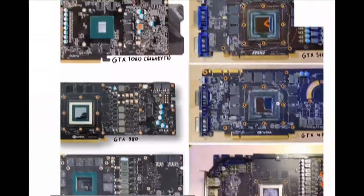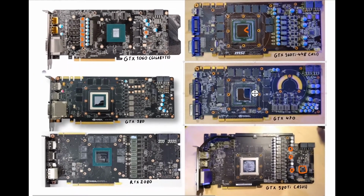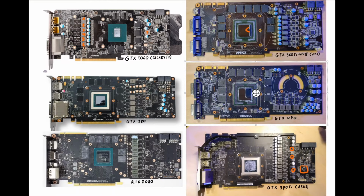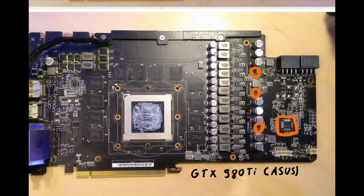So if you put it into the internet and you search for it, like you search for NCP4208, you will find a datasheet for it. You don't always find datasheets for the PWM controller, sadly. Like if you have an ASUS card, the PWM controllers will be rebranded, like they will be SHE or DigiPlus something, and you will not find datasheets for these because these don't really exist.